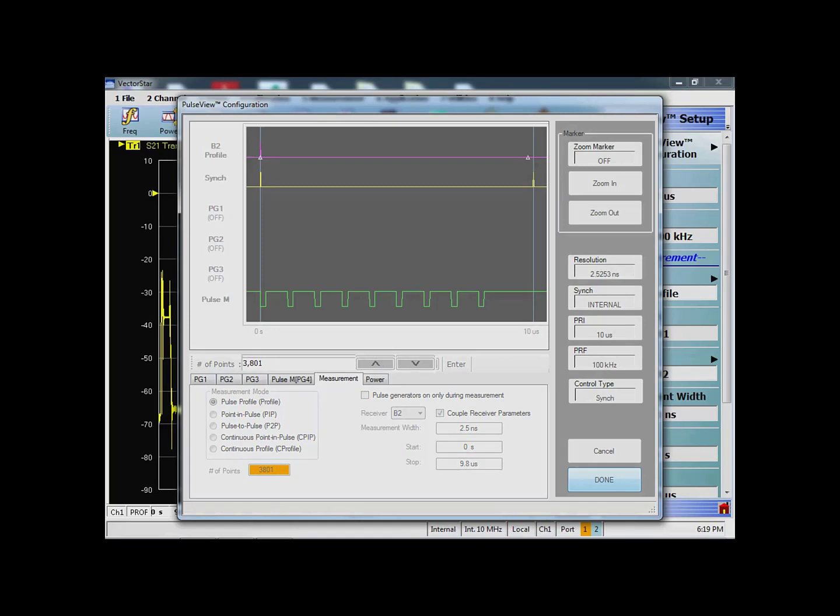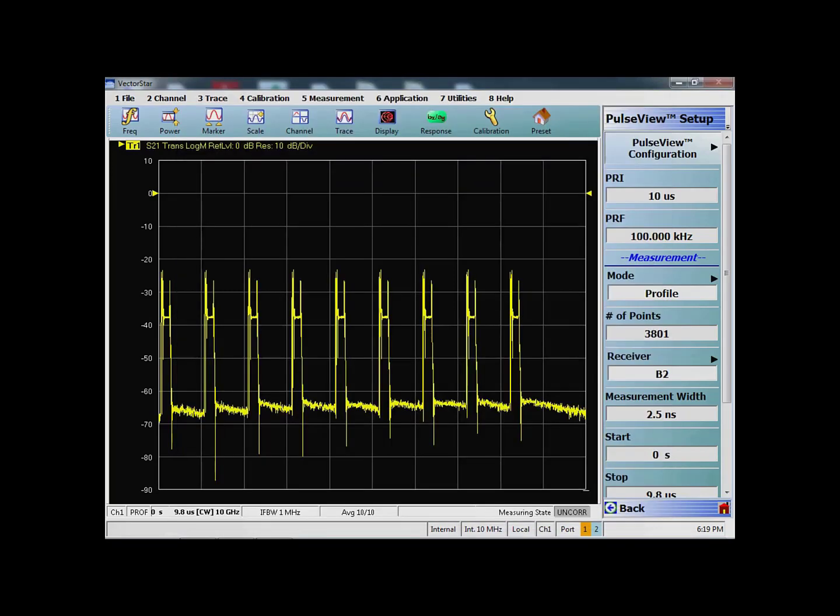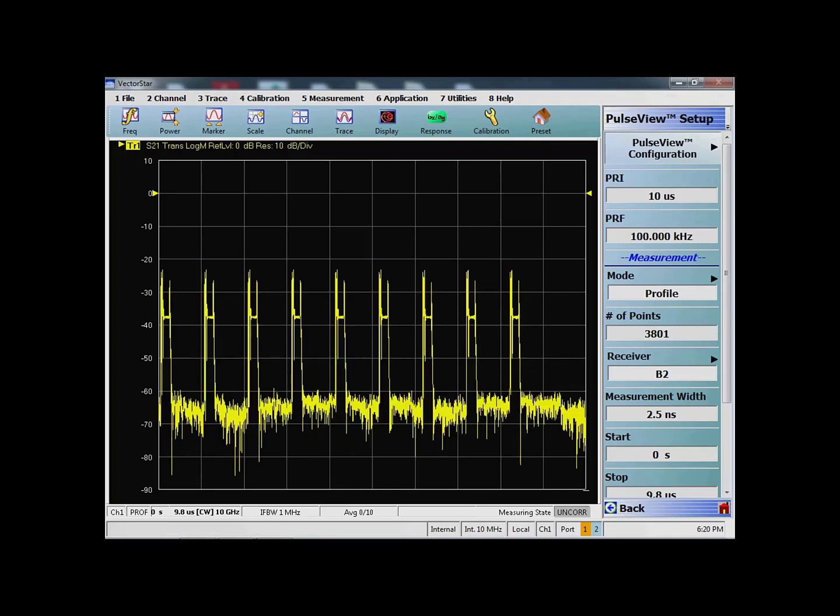Now it's going to take some time in processing, because for each and every pulse it's trying to process the data. The graph that you're seeing right now was done before, but whenever an update happens, that is the time you will be able to see the pulses as is. So this display right now is frozen. It's an older display because I was doing some settings, but you will see now this one has updated. So this is the first of the averaging. That means now you can actually see 9 pulses with the entire overshoots, the ringing, and the entire pulse in the complete manner.